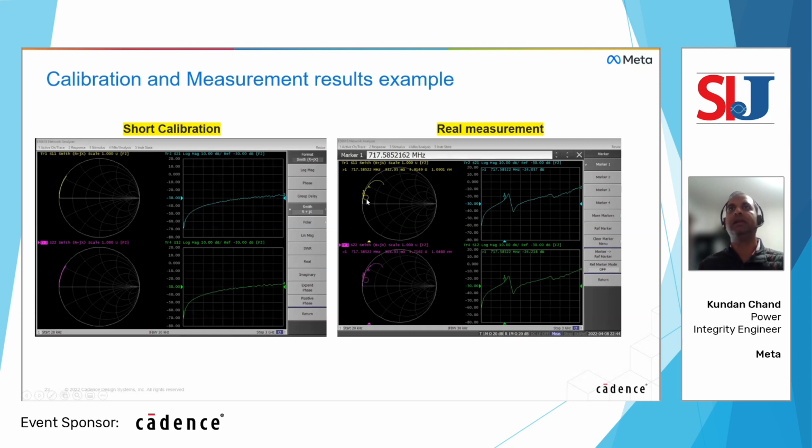You can see, depending on what kind of measurement we are doing, we can have some resonances at certain frequencies. On the right side, you're seeing the same thing in dB, or the magnitude only. So this gives us an intuitive feeling before making any measurement of how the calibration looks.